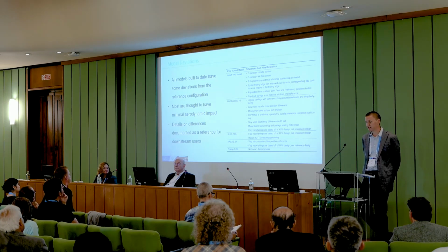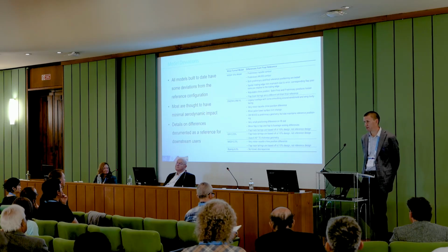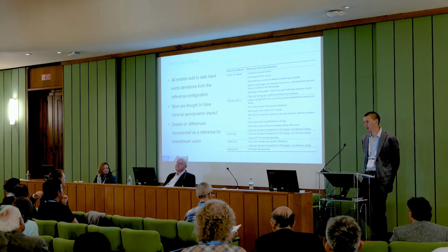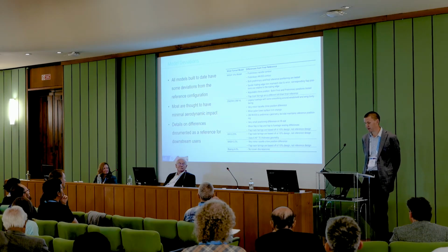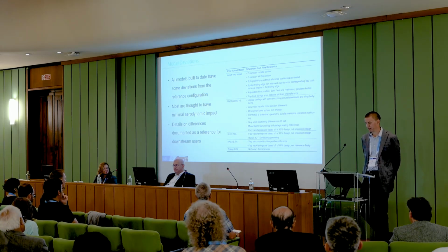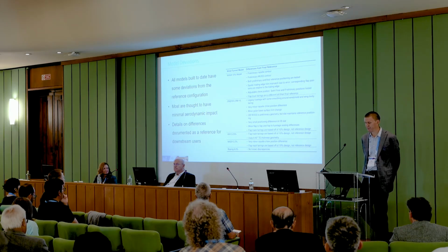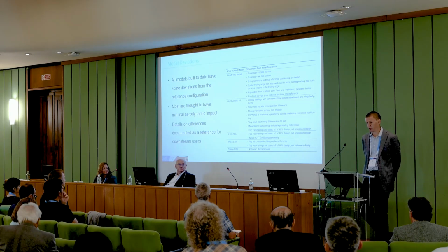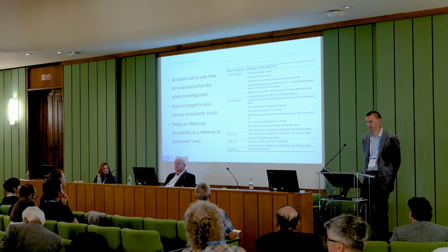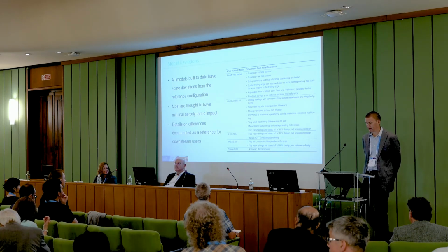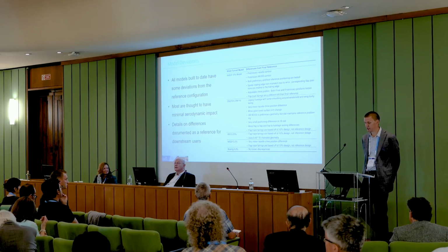The WUS, the wing under slat surface, so that's the piece of the wing that's exposed when the slat is deployed. Based on that, the definition happens based on the takeoff position, so you want it to seal wherever the slat ends up for takeoff positioning. So we ended up relofting that between the final reference configuration and what's on the NASA 10%. We did test both the preliminary and final reference positioning. This model features a spoiler trailing edge mismatch between the inboard and outboard. And then this one also had an adjustable chine position.